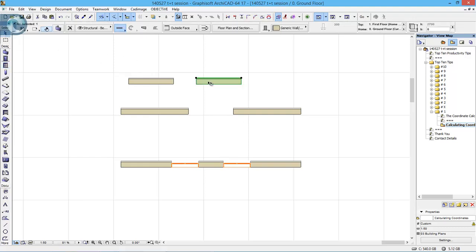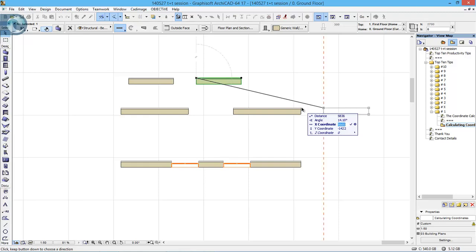As well as drawing, we can move things around. So if I take this wall, Control D to drag, I can rest it on this corner, so it's given a distance. If I press X, it actually shows the real XY coordinate of that point from the origin in the project. The number's not important. It is 4460, so if I do X 1000 plus, you see it adds 1000, so it's now 5660. And Y is 1442, so let's go down to Y and we'll say 1000 plus, and you'll see it now changes to minus 422 rather than 1422.